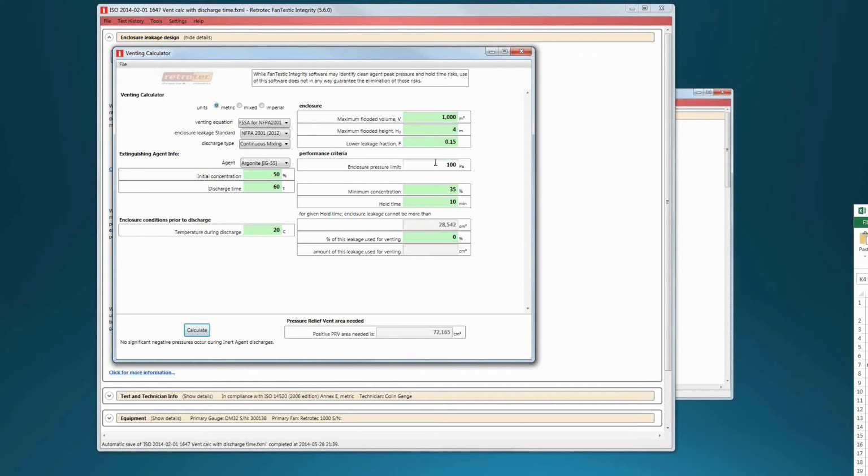Even the flimsiest walls will handle 100 pascals. We test with the door fan at 50 pascals. Our new door fans will easily go up to 250 pascals. So in some cases where they were concerned that the rooms wouldn't take more than 100 pascals, I would just turn my door fan up to 250 pascals and say, well, it's taking it now.